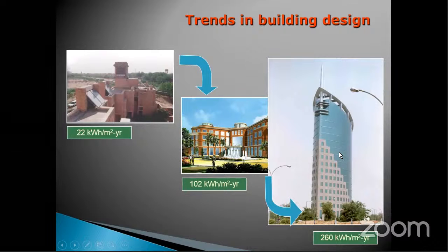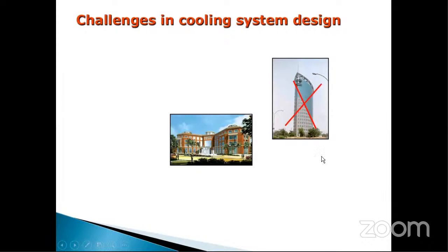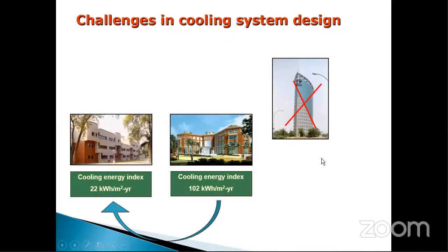Inside the building, the temperature which you are setting is exactly same, but because the systems were not efficient, the glazings were ordinary, the wall insulation was not provided. So that might be one of the reasons for this higher power consumption. So we have to ensure that we avoid having inefficient buildings and make sure our buildings are efficient.